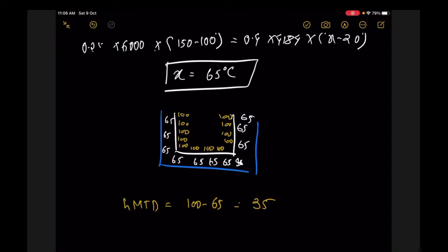Okay. Obviously, if you see any CSTR reactor, there will be a stirrer inside that. That is the property of a CSTR. So in CSTR, whatever will be the concentration outside the reactor, it is equivalent to the concentration inside the reactor. Same thing, whatever the outlet flow rate coming from the system, and whatever the temperature at the outlet, it is the same temperature which is inside the reactor.